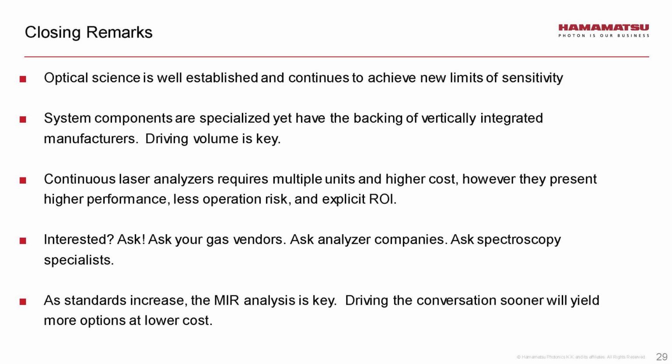You are going to need an analyzer for each separate species. In many cases, they could be a complementary system. So if you're looking at one or the other, you're definitely looking at an explicit ROI, lower cost of ownership of the laser system, because you're not dealing with those consumables. You're not dealing with that maintenance and calibration. And on top of that, you're mitigating your risk, because one analyzer down doesn't doom your process. And again, you're seeing much, much faster measurement cycles with a laser system.